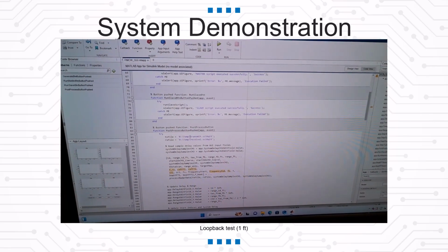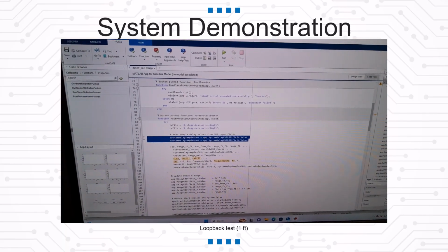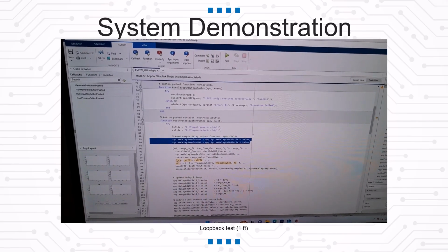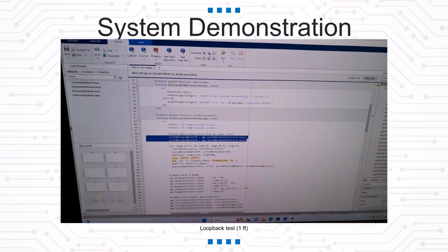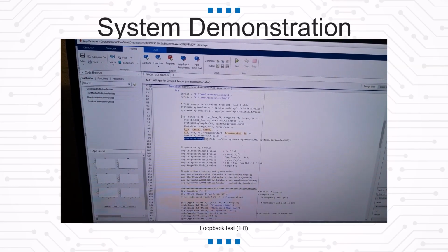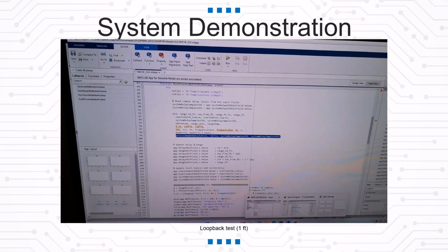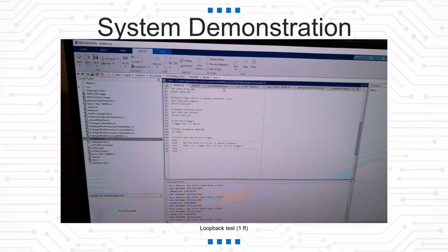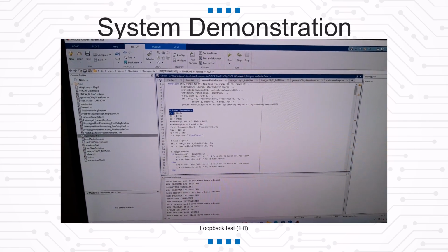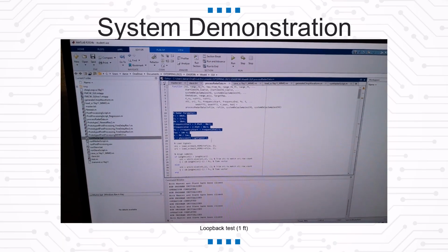And then we do the post-process button. By this time, we have a transmit and a receive file. We set a system delay, which offsets the inherent hardware delays, and then we run the process radar data function. The process radar data function has all the same parameters that were set in the software-defined radio.